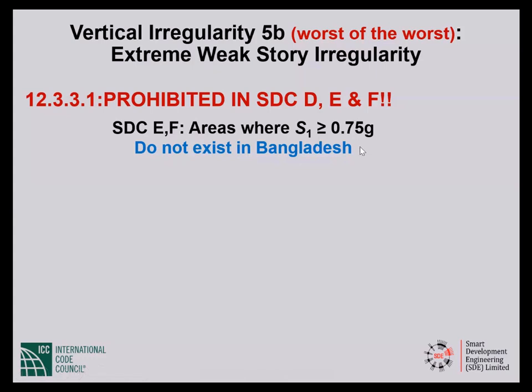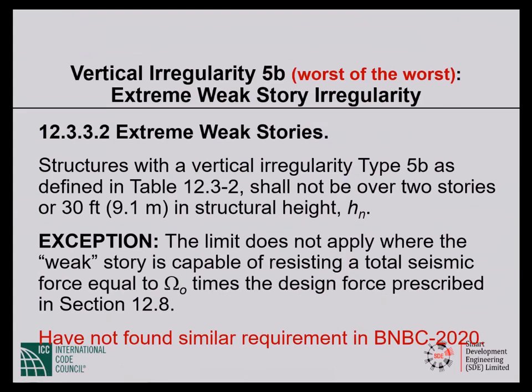I haven't checked if that is true in 2020 BNBC. I do not believe the prohibition is there, but please do check for yourself. I did not do a thorough check. ASCE 7-05 would not allow that, period, in design category D.